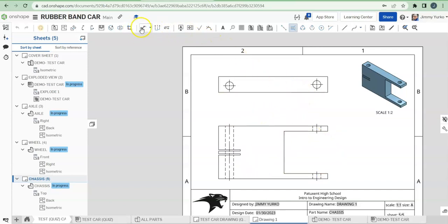And now it's time to go ahead and add dimensions. So we're going to dimension tool. So remember, always dimension the overall size for everything. That's the single most important. You need to know how big a piece of material cut this from. So the overall height is 2.5, overall length, and overall width or depth. So we have our width or length, our height, and our thickness.